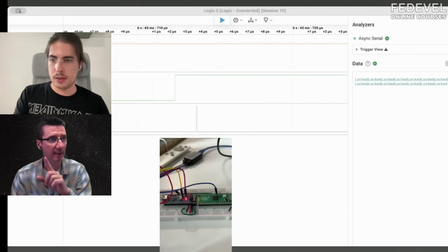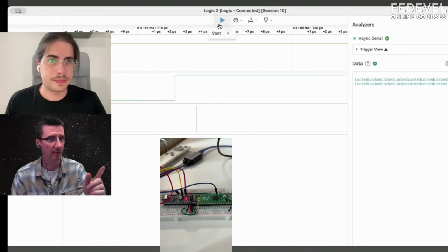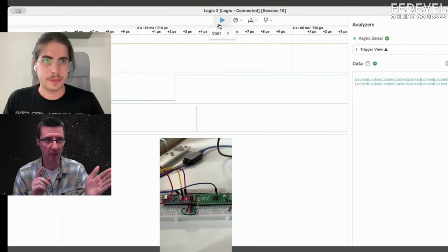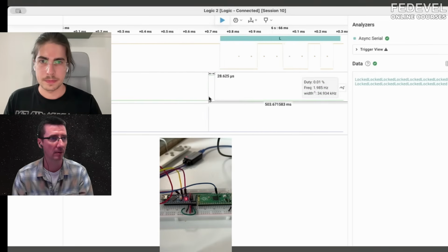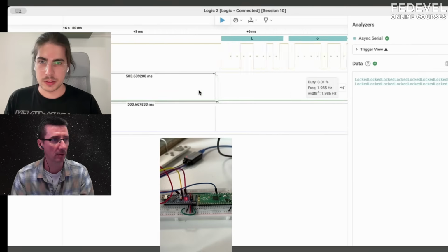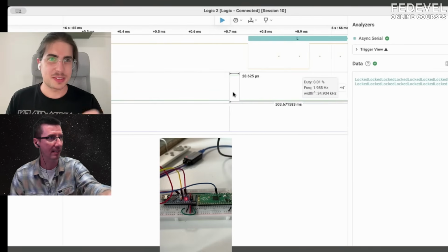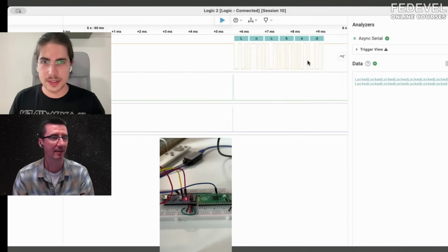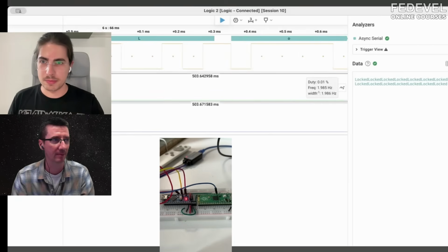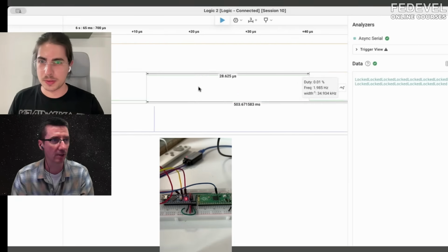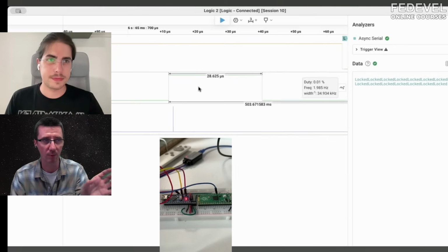And I have another question. The green one, that's the whole loop, like from 0 up to 255? Yes. And what is it doing in the other time when it is low? In that time, it's just waiting. So okay, I guess it also sends the serial output, doing other stuff. Yeah, okay, I see. Serial stuff. That's the logged text. Yeah, it's just random computations. I just wanted to be sure this 28 microsecond, that's exactly the loop which we would like to attack.